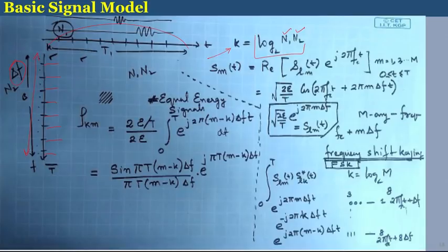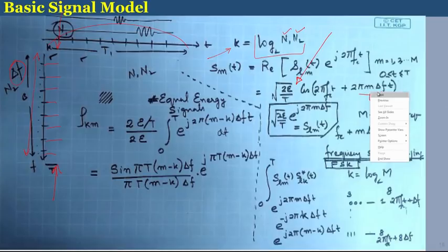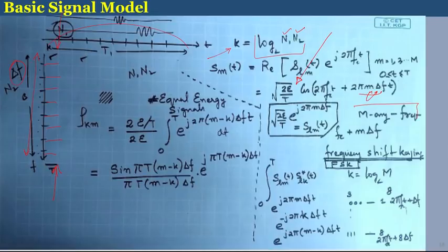So, we move beyond that, and we said that let us consider only one time slot, that means there are multiple frequencies available to choose from, but for every time slot. In that case we had also said that the amplitude remains constant, that is one of the important features, while we can choose the frequency by having a multiplicating factor along with the delta f, which is the frequency of separation. So, this kind of a signaling system is known as the M-ary FSK, just as you have M-ary PAM.